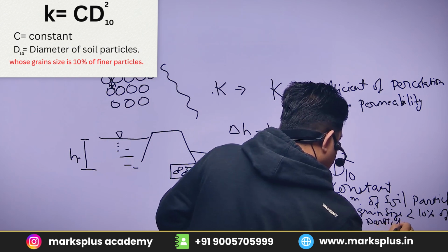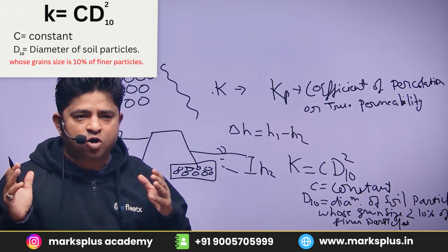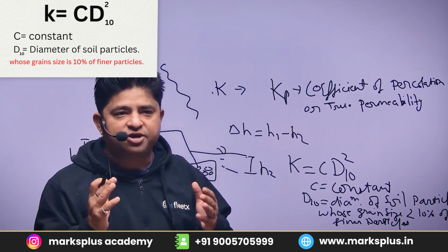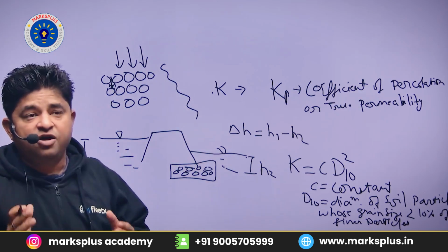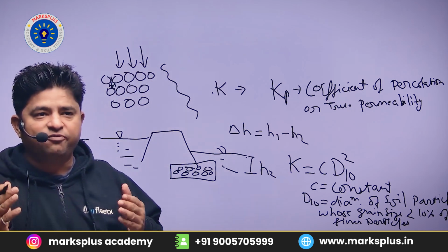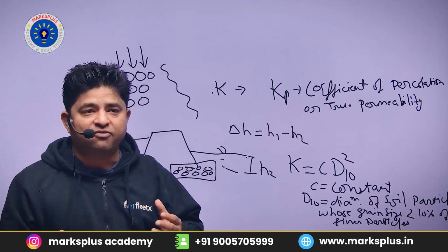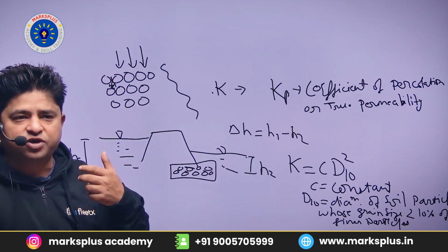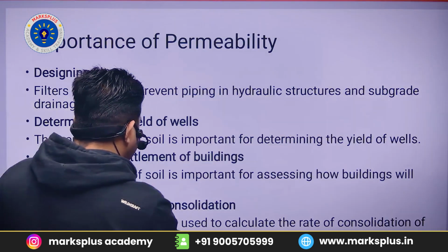Okay, so basically if we talk about dam construction, it is very important to provide our drainage filter at the bottom of the dam, and for designing the filter we should know the permeability of that particular soil, to know how much fluid or water can flow there if we are designing a filter. So the importance of permeability is in designing the filter.